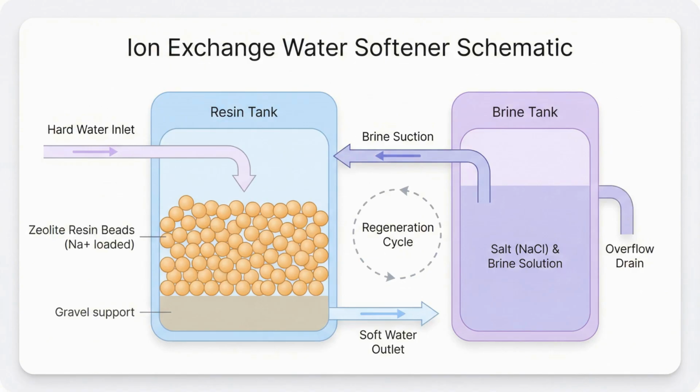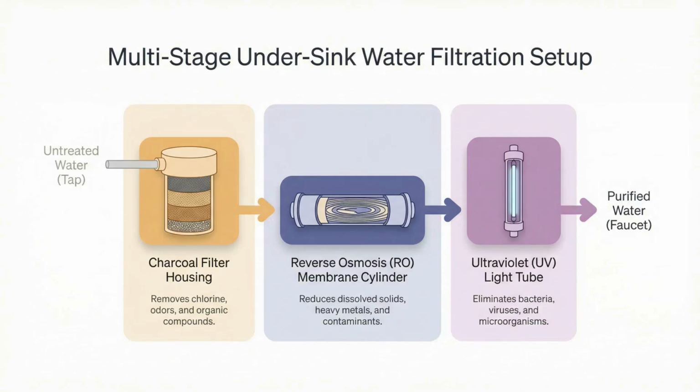For drinking water, advanced filtration might be necessary. A charcoal filter is great for removing bad tastes and odors. If bacteria is a concern, an ultraviolet light is used to kill organisms. And if you are installing a reverse osmosis or RO unit, remember that the highly purified water it produces is aggressive, so all downstream piping must be made of plastic, not copper.